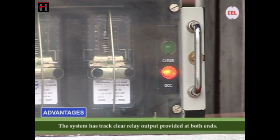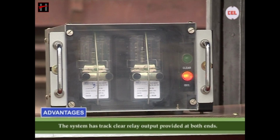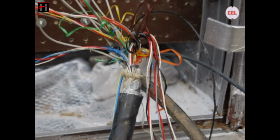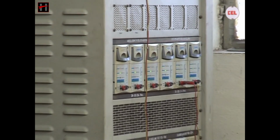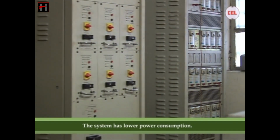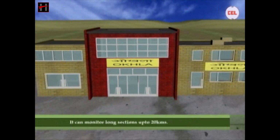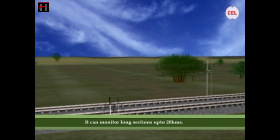The system has track clear relay output provided at both ends. The system works on one pair, that is half quad of cable. The system has lower power consumption and it can monitor long sections up to 20 km.